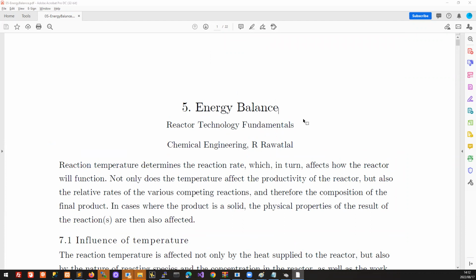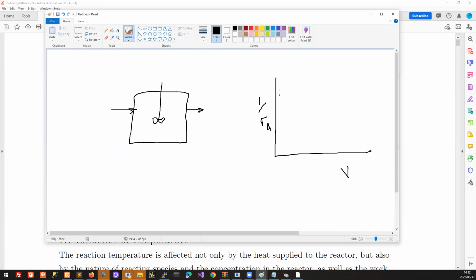So in this energy balance, as we said, in the isothermal case, we've got the temperature being the same at all points across this reactor. And if we think about most reactions, that's simply not the case. You have some collection of reactants, and even in the simplest possible case, even if it's just A going to B, then the energy state between those two is generally different. So the molar enthalpy of A is different to the molar enthalpy of B. And what that means is our molecules are in a different energetic state.